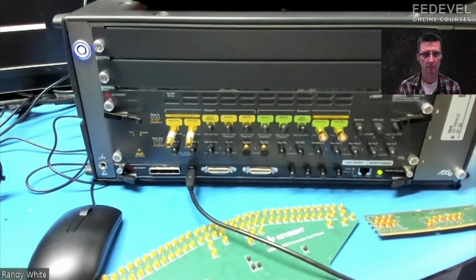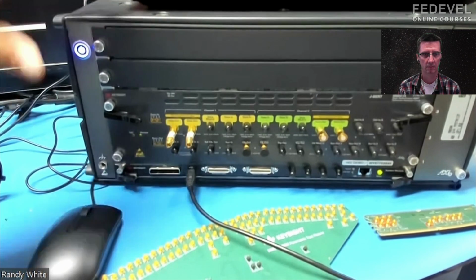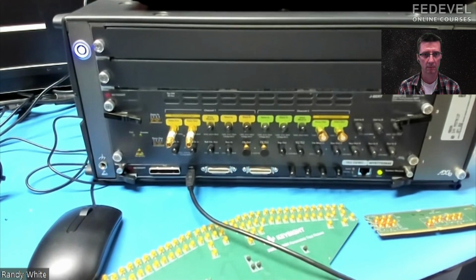So the receiver has a way to compensate for PCB losses and ISI, and its decision feedback equalizer. In order to test that, the way it's implemented could be different from one manufacturer to the other. And so this whole setup allows you to simulate worst case conditions and then check, is the equalizer, is the DFE working properly?